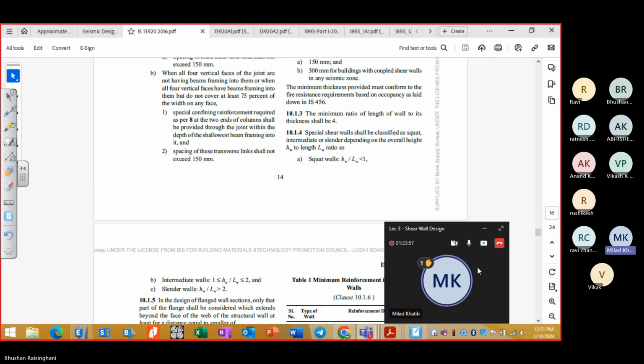At first, those two shear walls each have their own behavior and work separately. Once I add this coupling beam, now all of them behave and work together and become a deeper, more functional element. Okay?